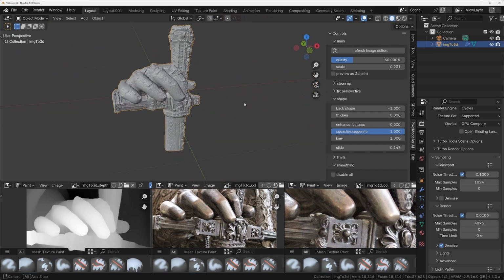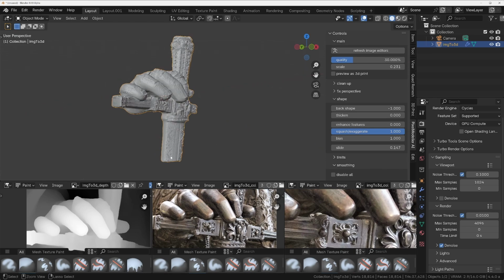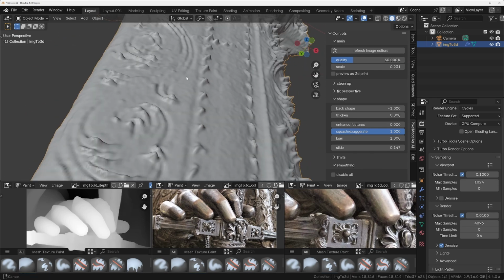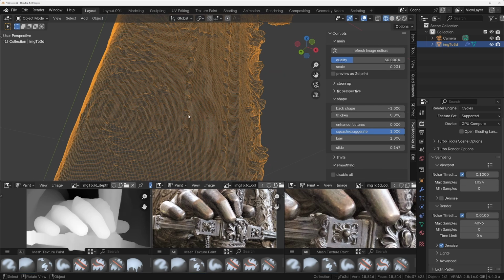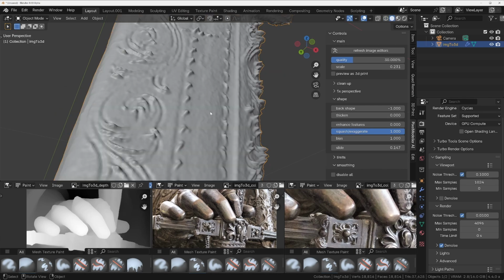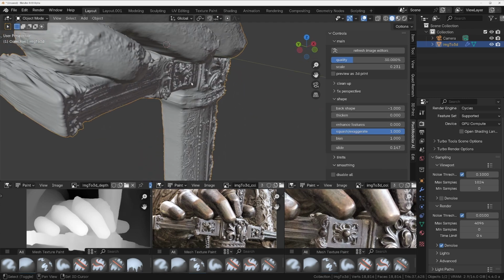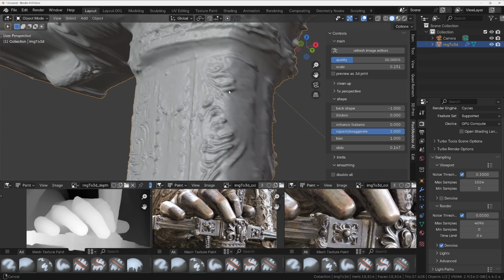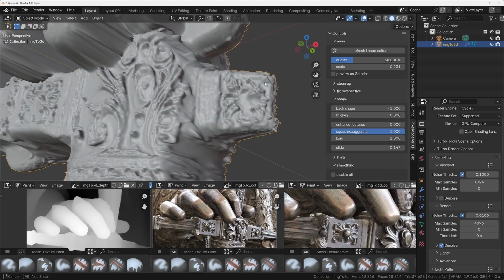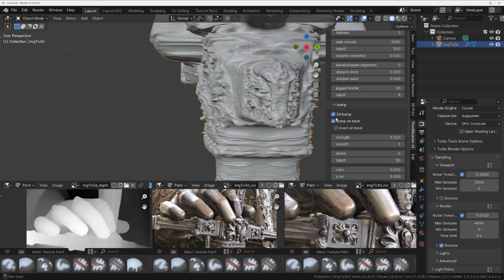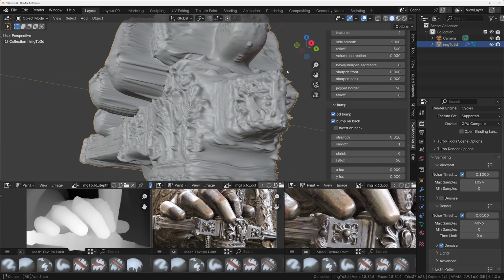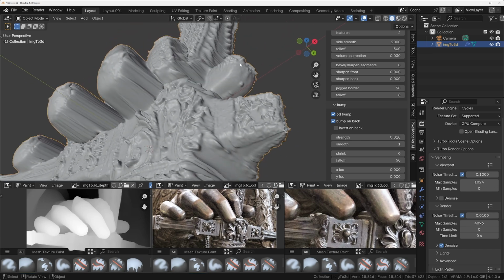And what I want to do is change this without losing all this really fine detail. I want to get it more sort of a game-ready asset with better topology rather than just being loads of really tiny quads. Now, one thing I do want to do as well before I do that is just make sure I don't have any overlapping areas of geometry, because the 3D bump here can generate overlapping areas of geometry, because it all depends on the normal of the object.